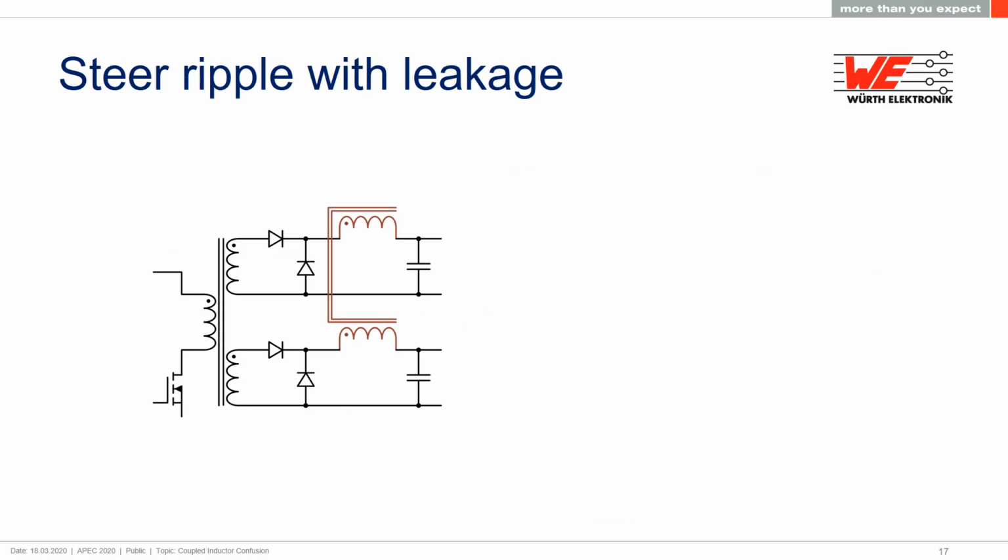This is just an example of the schematic showing you how we draw the multi-winding inductor. We use the core lines as the joining element. One of the main cautions when you use this type of inductor is that the turns ratio between the individual inductor windings has to be identical to the turns ratio of the transformer outputs. If this is not the case, there would be circulating currents caused by the voltage differential, which would cause increased losses among other problems.